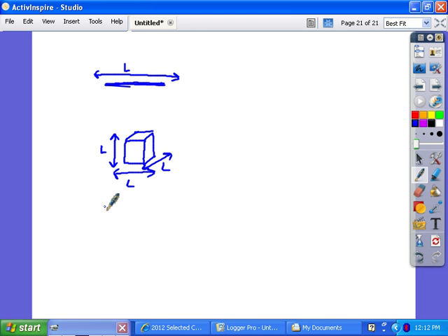So the reasoning behind alpha being so closely related to beta is because you now have 3 different directions that this can expand itself into. Instead of just traveling in that singular line, it now can expand itself in those 3 dimensions, and to account for that volumetrically, you got 3 times as much. Okay? That's how those two are actually tied together there.